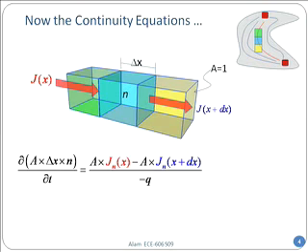Okay, so this is almost done. If I didn't have any other process, in fact, this would be the equation that will tell me how many electrons are coming in and out. Now remember, this J sub n are the fluxes that are coming from the contact, right? These are drift and diffusion current. But of course, there is another current that we can also think of: if you shine light, that's a third source from which electrons and holes can come. So in that case, assume that the top yellow arrow, pointing downward, is light shining on that sample. So the electron is not coming from the contact, but coming from outside.